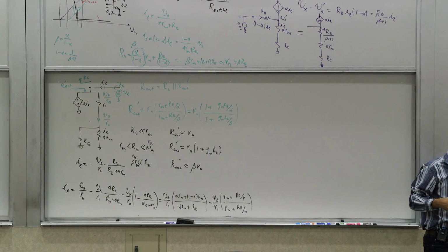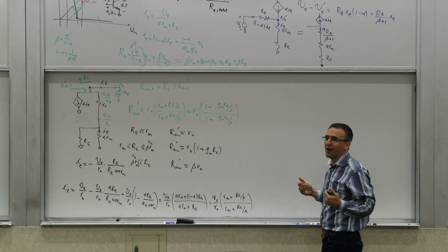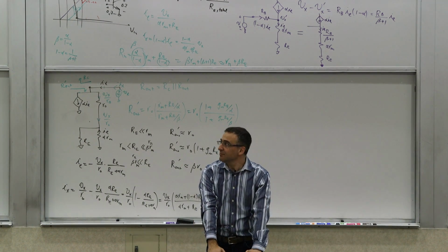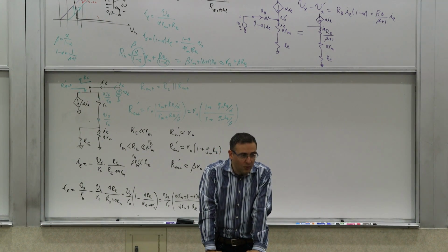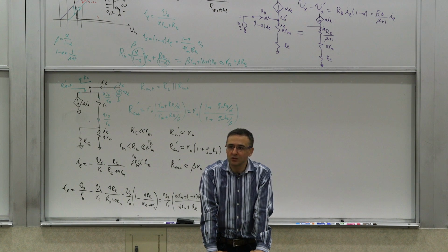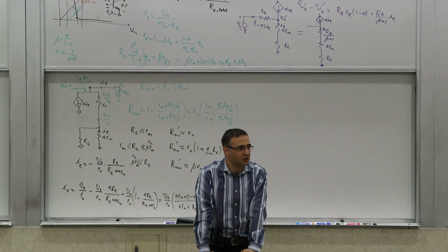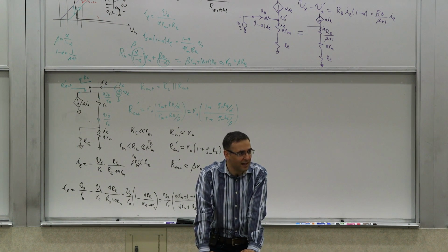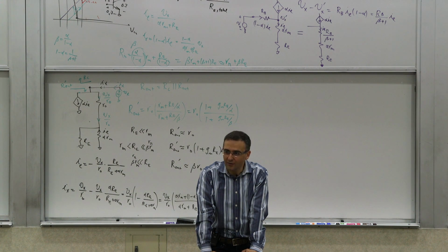Why do we get so hung up on the output resistance and how high it can be? The reason is simple. Because the way to get gain is to have a Gm, a drive, and a load resistance. And the only way to increase the gain, really, is to increase one of these two. Either the drive capability or the output resistance.